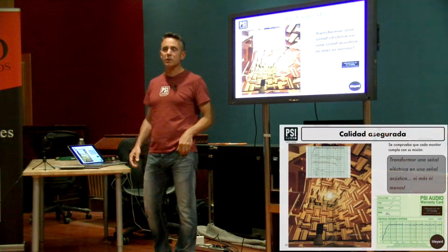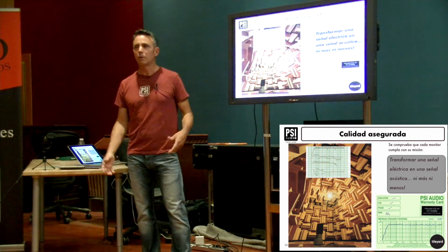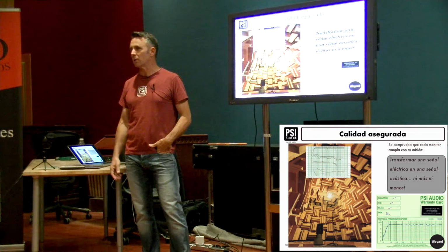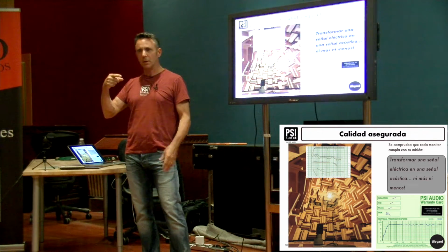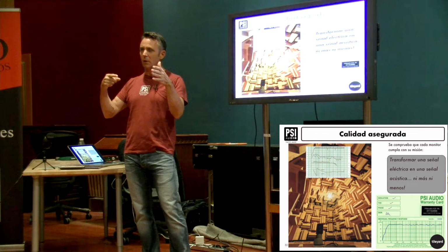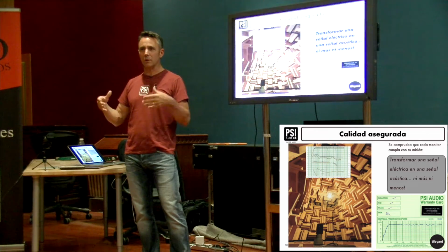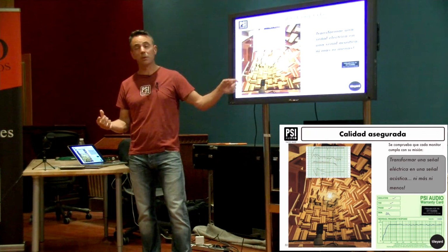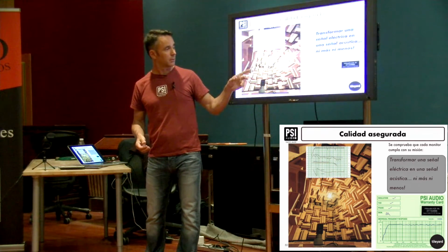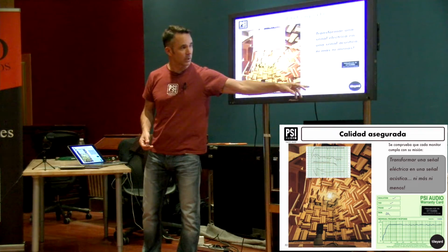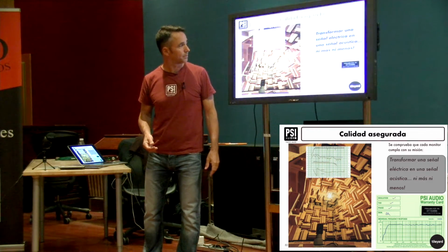If the role of a speaker is to transform an electric signal into an acoustic signal, well, you have to check the speaker to make sure it does that job. So you inject a signal, and you measure what comes out with a microphone, and you want to measure what comes out of the speaker and not from the room. So you need a room that's got no echo, an anechoic room. We do this for every single speaker, and every single one gets its frequency response curve.